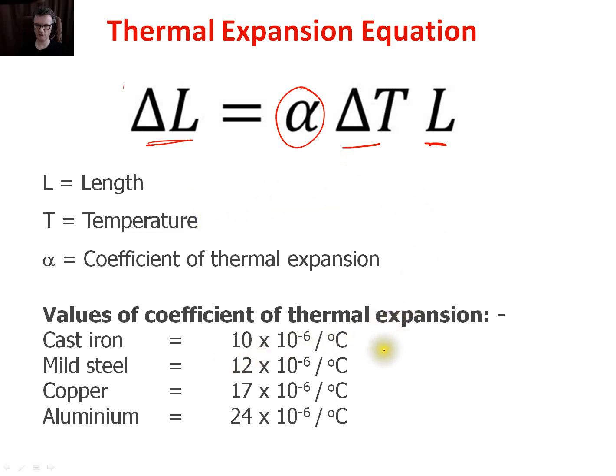And for ferrous metals, so for iron, for example, it doesn't expand much, nor does mild steel, so that would kind of imply that perhaps these are good metals to work with if you want to have changes in temperature. That's not true, because say something like cast iron, you certainly don't want to be taking that down to cold temperatures. It becomes very brittle. And then we've got aluminium, which seems to expand a lot in contrast with iron, and yet you can make your planes out of aluminium, of course, and not iron. Of course, there's a question of density there as well.